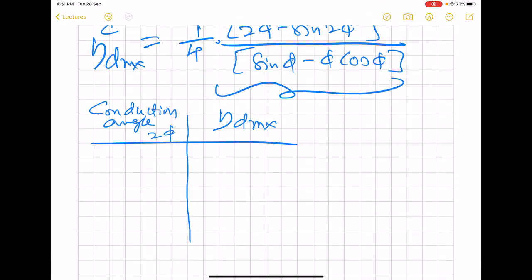So since we are claiming this to be class C, we will take conduction angle which is less than pi but greater than 0. So we will take say 120 degree. And if we take this, we get efficiency which is 89.68%. And this is, you can recall, greater than that for the class B. Now we can further reduce the conduction angle and let us say that take 90 degree.